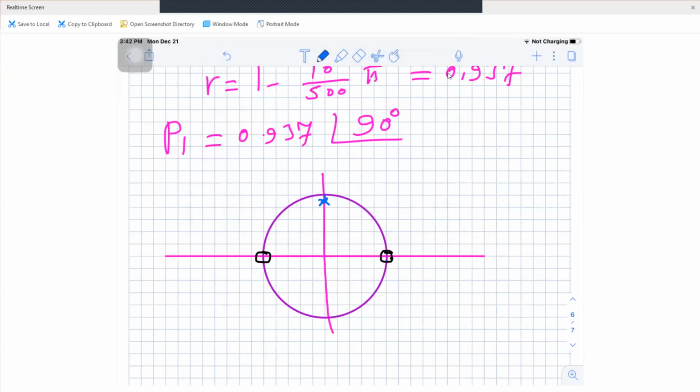Now, look please at this important point. We said in previous slides, a very important note, and you have to keep this note in your mind. To get real coefficients of the IIR filter, the poles and zeros of the filter either lie on the real axis, or they have to be obtained as complex conjugates.